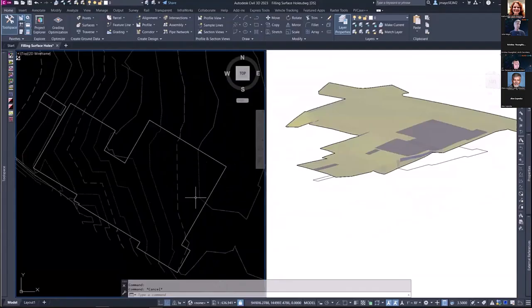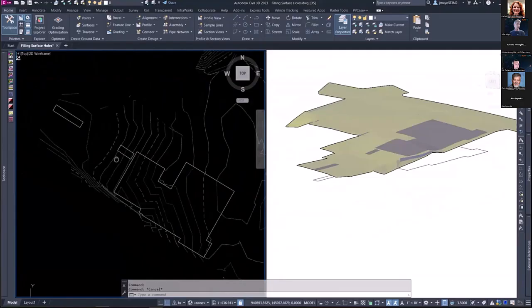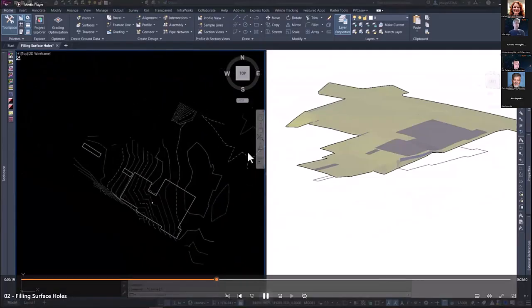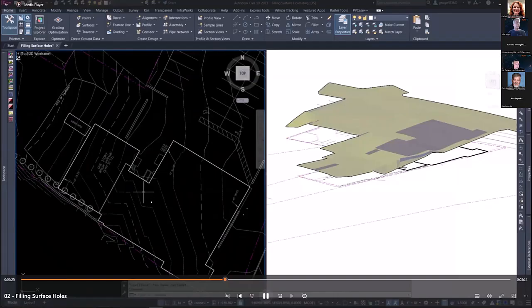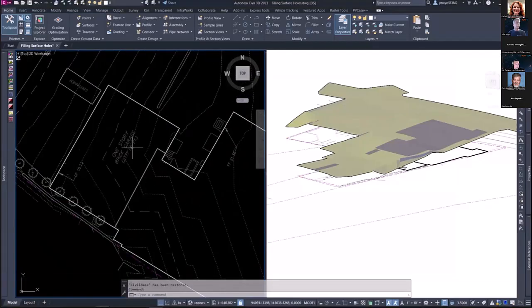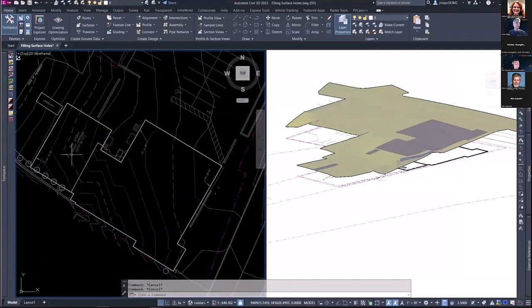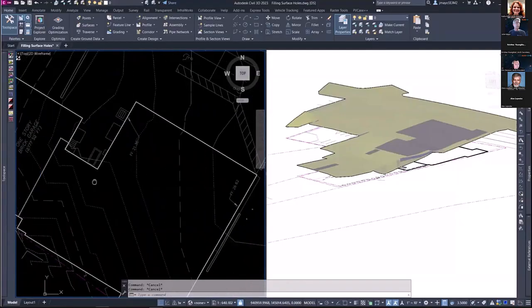And if you wanted to clean up contours, you could use a couple of polylines, flip some triangles, do what you want, but there's the quick and simple solution. All right, let's go one step further. What if the main building was staying and we were only going to demolish the garage? The easy fix for that is just to model the floor of the building and let this fill in, and the surveyor was nice enough to provide us with some elevations.